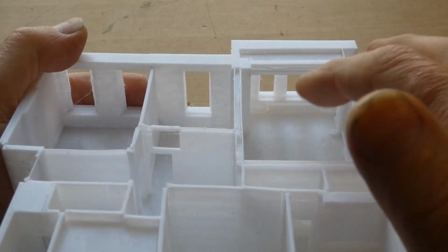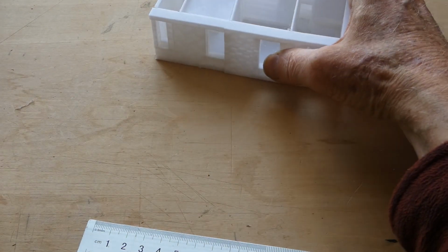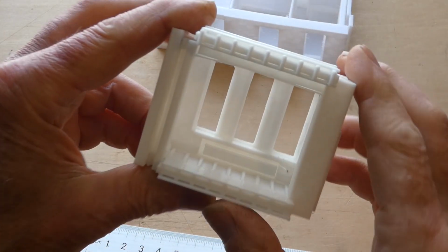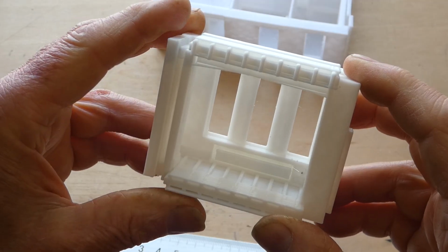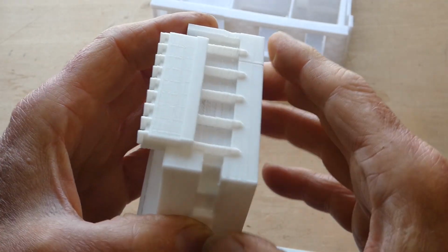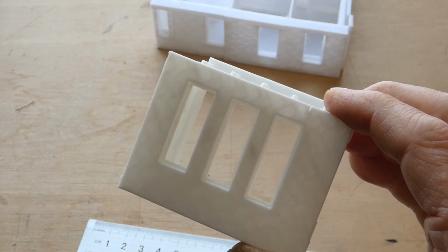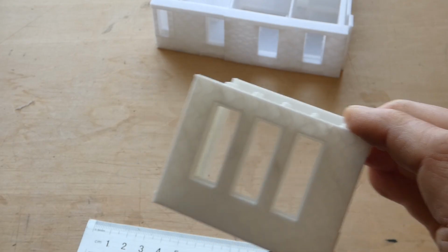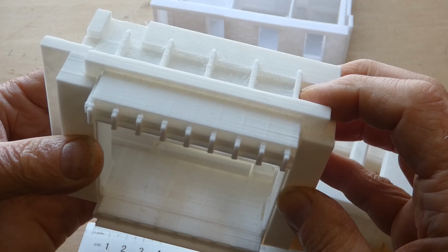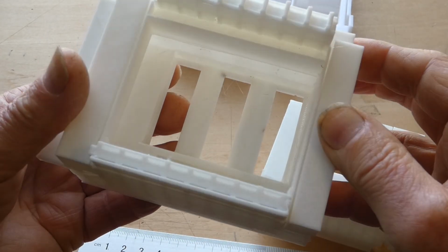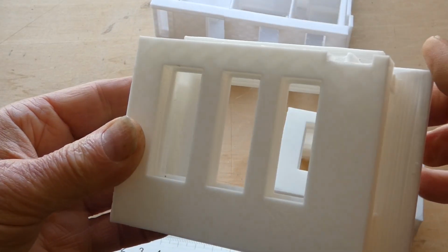In this case, I took that now familiar model of the historic apartment, and in one section I added additional details to the floor and ceiling to represent the construction at the front facade. I did this in order to support discussions with the construction team who were planning on stiffening the floor structure. Again, such changes in resolution are often used by simulation teams to explore an issue on a small scale before applying it to the whole model. In other words, constrained introduction of complexity.